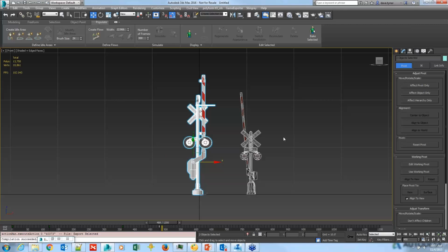You can't really see it, but it happens, and I just like to keep it editable mesh. I like to work in editable poly, don't get me wrong, but for Trimble models, I try to keep it mesh as much as possible, only because I know what to expect. I don't want to throw another wrench in the works by converting it to a poly and then having it undo some things I have just done to clean it up. You know what I mean? Yep.